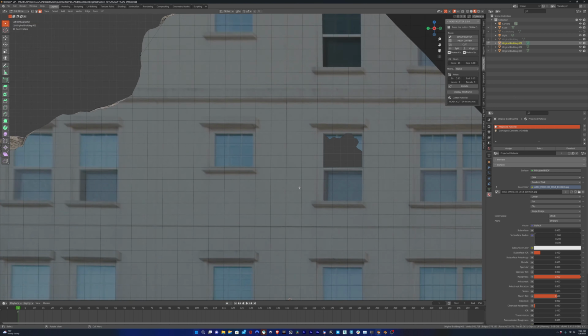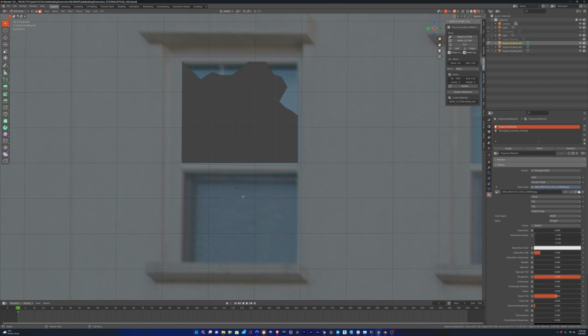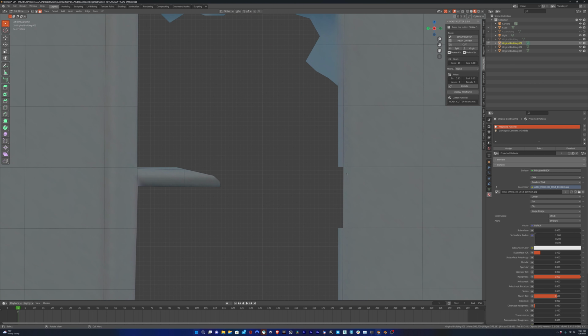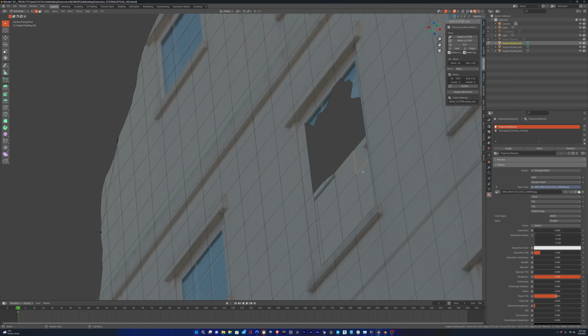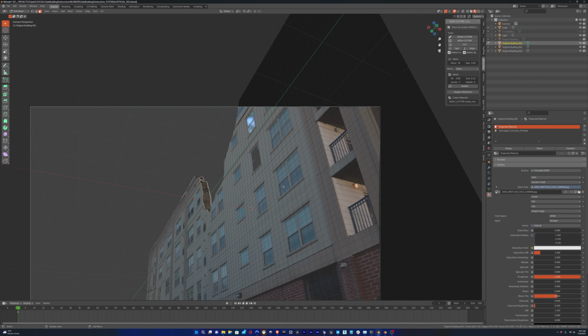One of the other things that I like doing is after we break the windows like this, we can actually break the frame. If you deleted a little too much there, one of the things you can do is just go into edge selection mode, select those two and hit F, and that'll fill that back in. Now, again, we went back into the camera view and we're seeing some of these things here. So we want to delete these. And now we have a broken window there.